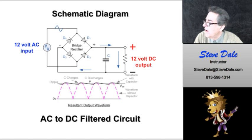Here's a schematic diagram of an AC to DC circuit. We, as low voltage contractors, need smooth direct current voltage sources in order to work with our switching systems and so forth. So how we do that is we take an input from a class 2 type transformer, that is an alternating current transformer that's plugged into a receptacle. You take 120 volts from the primary side down to the secondary side, which would be fewer coils, and you would drop the voltage to whatever you had desired.